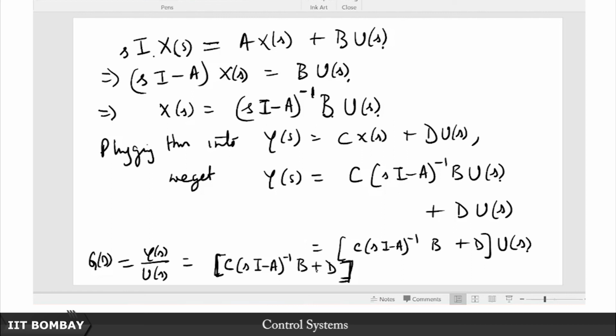By that I mean, look, if you are given a transfer function and you are given the input, you do not need to actually carry out the convolution in the time domain. You can take the product of the Laplace transform of the input and the transfer function of the system, and then take the inverse Laplace transform of that product, right.